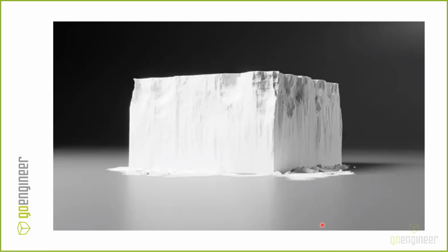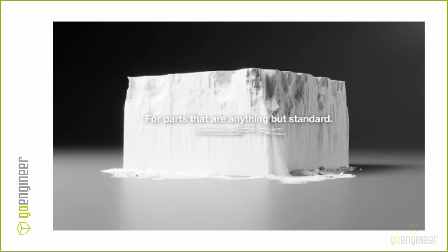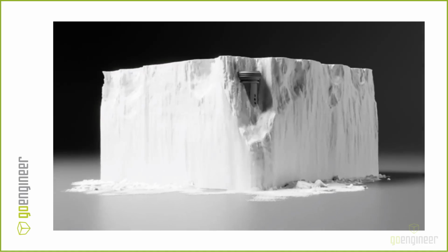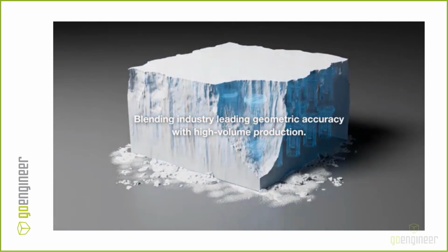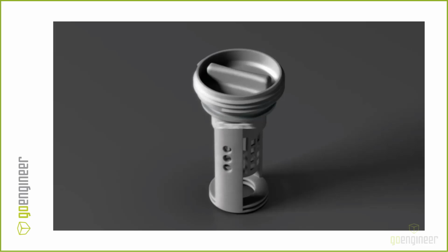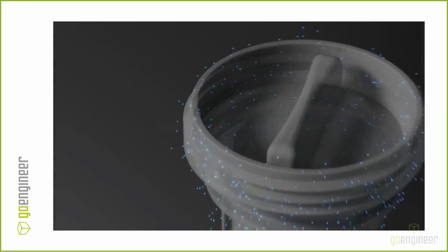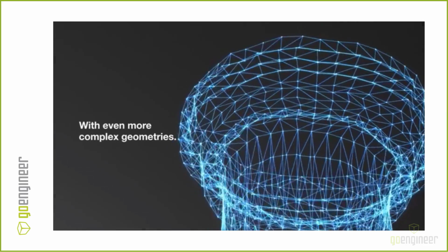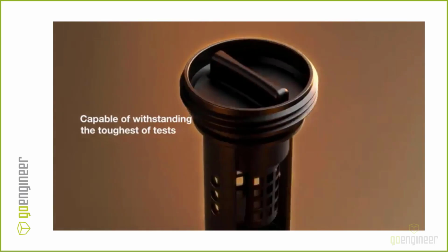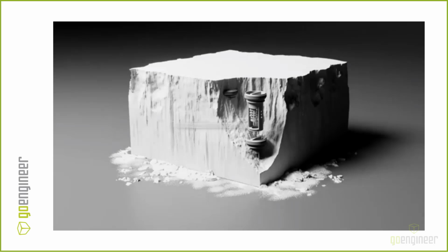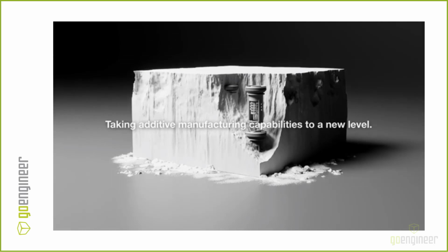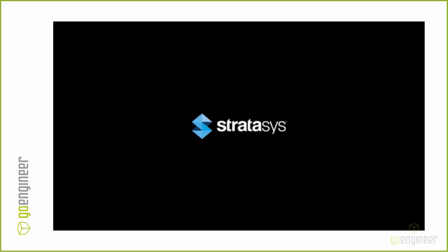One neat thing about this, I wanted to show a short clip announcing the recent addition of a new material to the H350 lineup. It is PA12. But I also like it because it showed what a build produced using SAF technology looks like before going into post-processing. You have to decake your parts and get all that extra powder. And as you can probably imagine, dealing with all the small particles of powdered polymer introduces a layer of complexity to this technology, but overcoming that challenge is rewarded with the ability to produce highly precise, additively manufactured parts at scale.